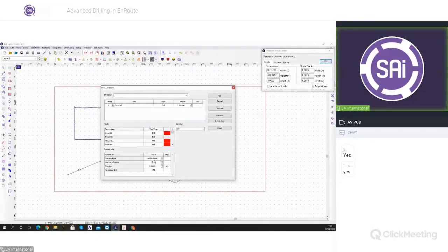So we can define a number of holes. Let's say we'll just pick 10 of them, and we can define a spacing here as well. So we'll set them every, let's say, 70 millimeters. And then the spacing type, you can actually choose to prioritize several things. You can choose to hold number, hold the spacing, hold numbers at a certain spacing, put it at all corners, just the inside corners or the outside corners.